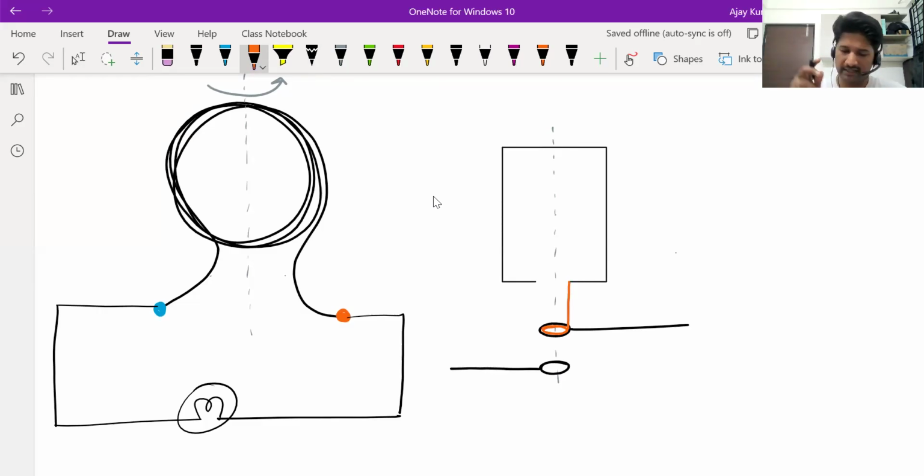So that orange wire that I am showing here is not rigidly connected to the slip ring. It's connected to the coil, yes. If the coil rotates, the orange wire comes to the left side, but it's not rigidly connected to the ring. So on the ring, it just slides to the left side. And then imagine the other end of the coil. Make it pass through this ring. It doesn't touch this ring, the radius is adjusted that way, but it touches the other ring.